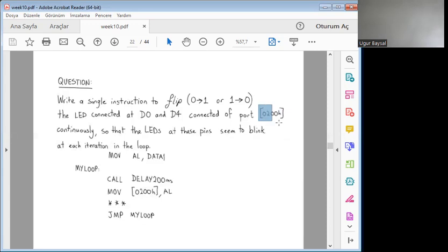For example, assume the address is defined for the LEDs like this. You send some data to this address, which makes the corresponding bit for the LED be on if that signal is high. Since the microprocessor is so fast, you want this on condition to be sustained for some number of half seconds or 1 second, so that a human eye can see it.